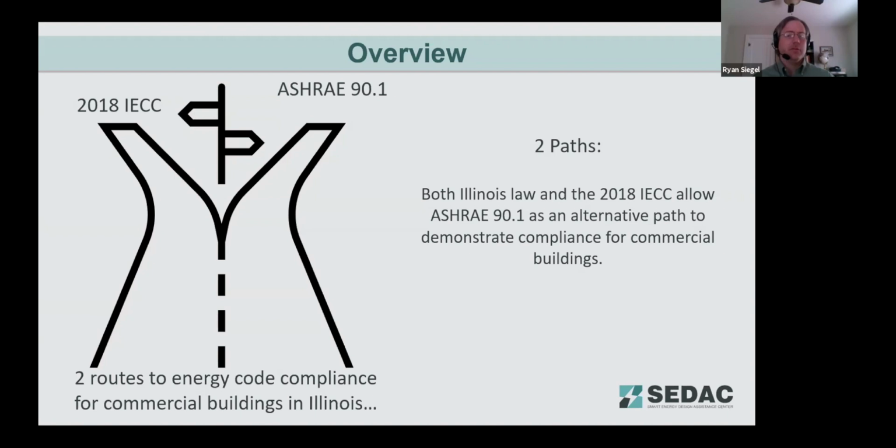It's a little less common in the energy code where code officials will require an older code to be used, and not perhaps allow the newer code to be used for demonstration of code compliance. However, that's because there's not as much interplay with the energy code as there is with the other building codes. So using a newer energy code is not likely to have a substantive impact on compliance with the energy code. Also understanding that many jurisdictions, because most compliance is demonstrated using the IECC, there may be some learning curves for the municipality for 90.1, regardless of if you use the 2016 or the 2019 version.